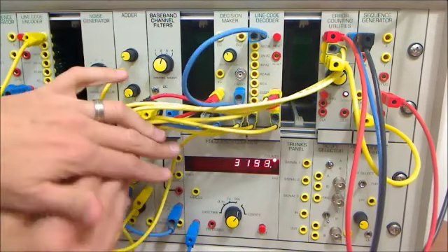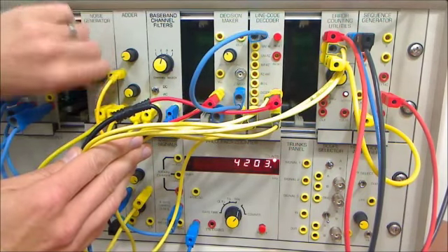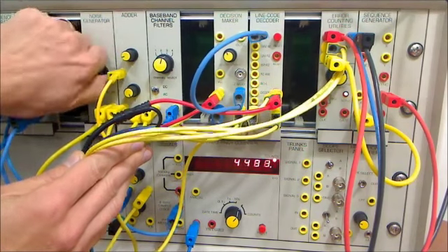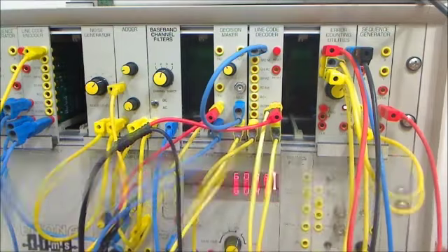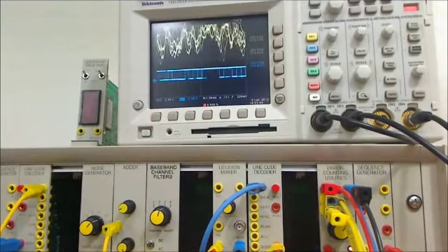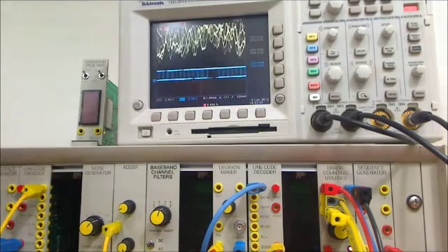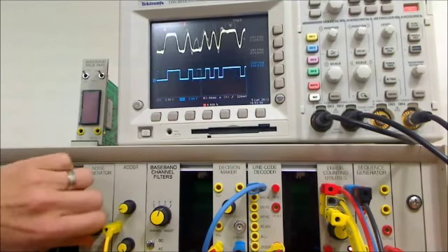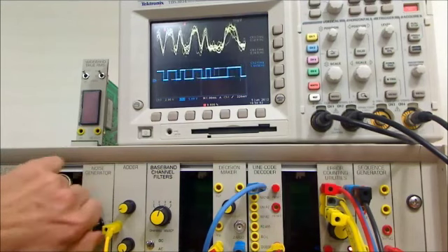You can see a large amount of errors accumulating. Reduce the noise, you see there's no more errors. So a lot of errors in the channel. If we have a look at this on the scope, pan back up to view the scope, you can see the signal with the maximum amount of noise. It's not an eye pattern anymore because we're not synchronized. Take away the noise and you can see the signal with no noise, signal with lots of noise.